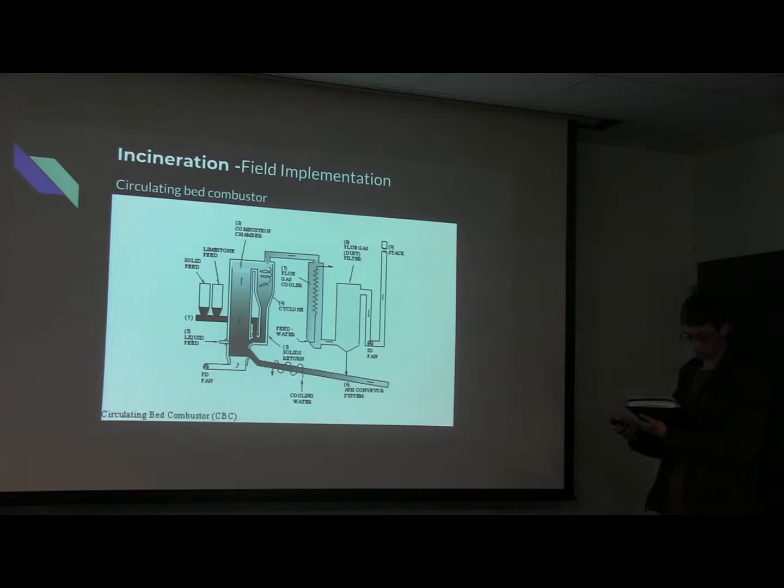In the combustion chamber, particles are held in a fluid-like state and are eventually passed on to the cyclone. In the cyclone, the denser particles fall through to be re-incinerated or passed on as waste through the bottom, while flue gas is passed on above to another chamber to either be re-incinerated or go through other processes.